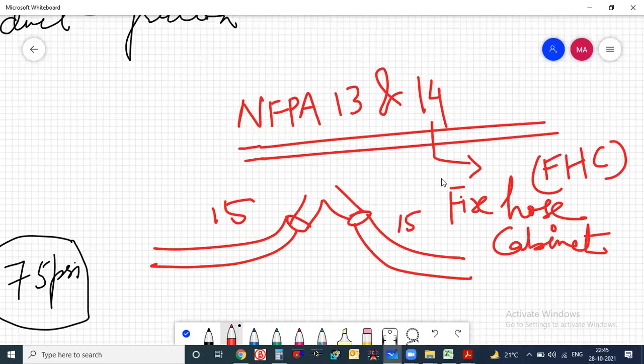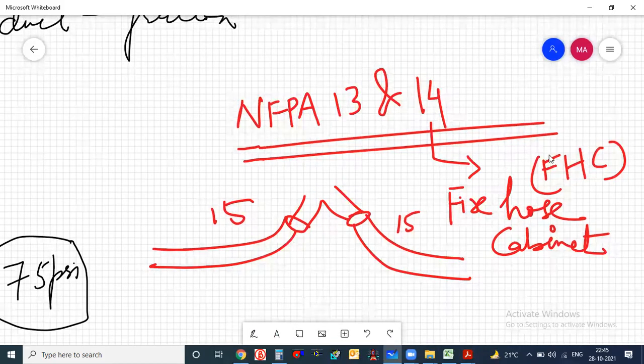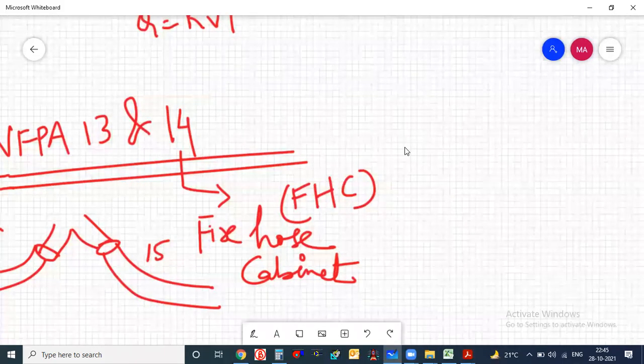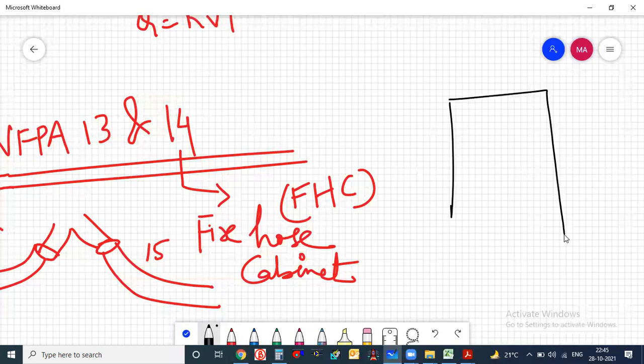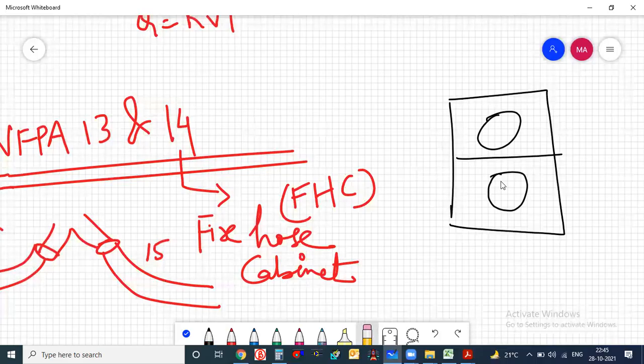No, Mr. Atif, I fixed this one. There is double cabin. Upper half, it will be hose reel, the 1 inch hose or 40 mm. Downside, there will be 2 inch and a half, like a coupling joint with 2 inch and a half hose, 30 meters as well. And there is powder extinguisher downside as well. Yeah, it can happen, but I haven't seen like that. Like one side you have 65 mm, one side you have 40 mm. I saw like this.